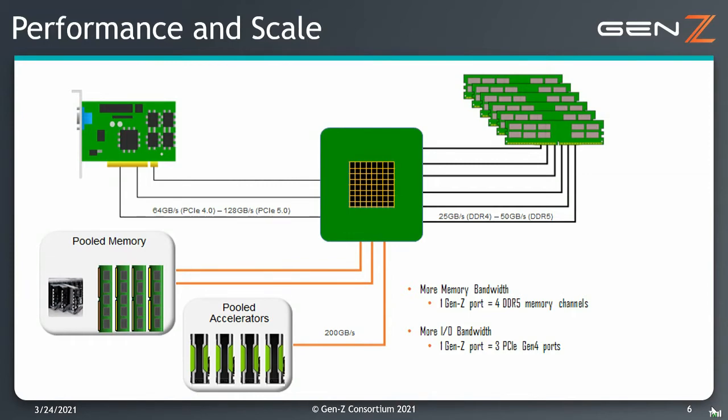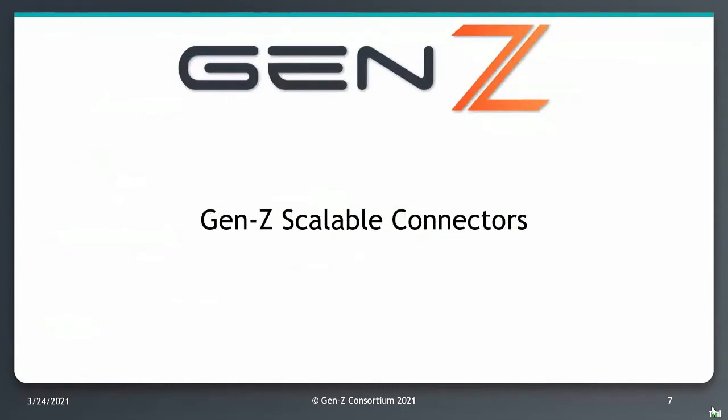So with that, the GenZ Consortium has had to design high-performance connectors, robust connectivity, and new form factors for the accelerator functions such that they can be plugged in and added to the infrastructure. And then the switching and the pool of resources can be allocated by a fabric manager and controlled so that data can either be segregated and protected from other processing engines or shared and grouped together, depending on the application requirements. So with that, let's hand over, and Matt, let's have a look at the actual devices and performance connectors and functions we have. Great, Tim.